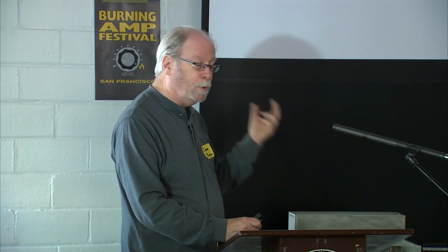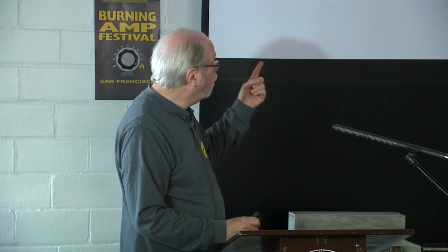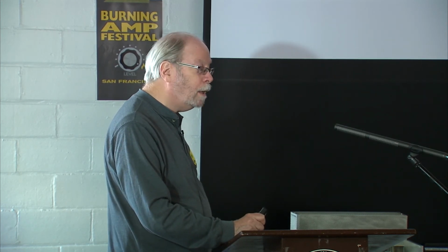And then the most exotic thing out there are these Radiometer Copenhagen boxes that are designed to measure the distortion generated by, like, a pure resistor. The one I have actually has a residual of -170 dB on the third harmonic, which is absurdly low. But if you put a mica cap on there, it'll show you that its distortion is 30 dB higher than a good polystyrene cap. It's a very useful gadget if you need to sort parts. There's nothing like them anywhere, and they're really hard to find.